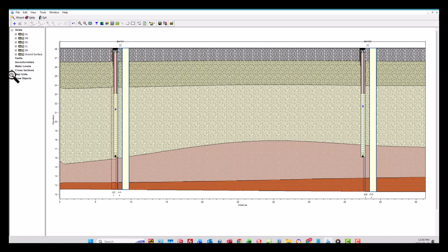When determining how to connect the strata between borings, wells, and intersecting cross-sections, the program looks at the strata names, lithologies, and thicknesses. For best results, the strata names used in the borings and wells should be unique and be kept consistent between borings and wells. These names are not shown on the boring and well logs.